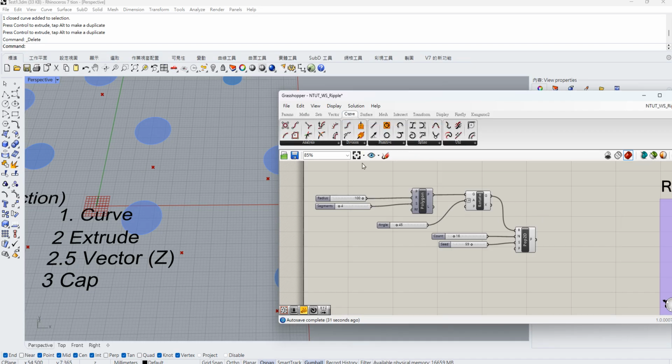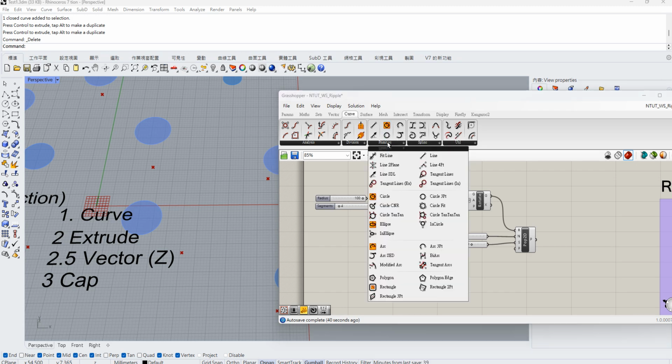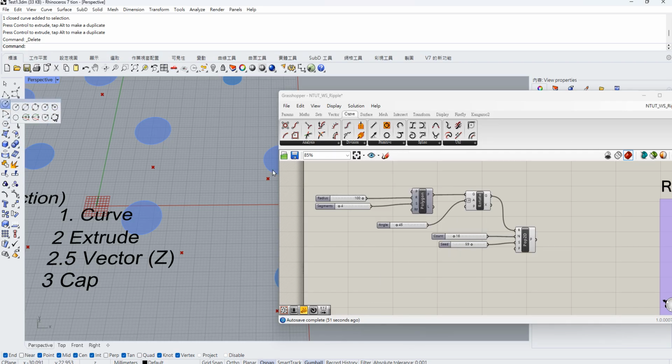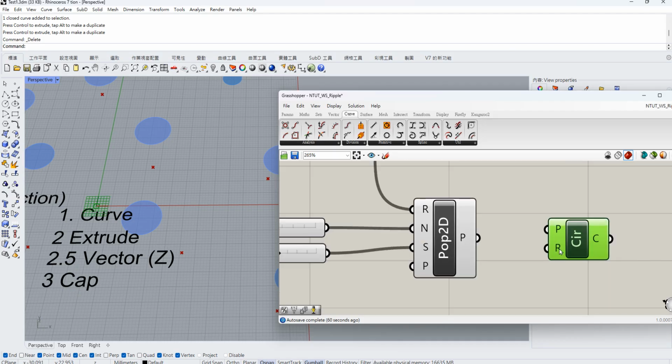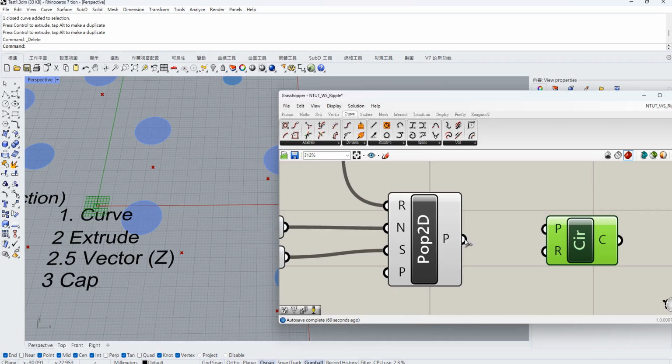Let's go to Curve and go to find Circle. Inside Rhino Grasshopper, there is only one option for circle, unlike in Rhino where we still have many things, like Circle 3PT, Circle V, etc. But the one we will use still will be the first one, Circle. Go to find Circle and two input points. Just choose the first one, points.